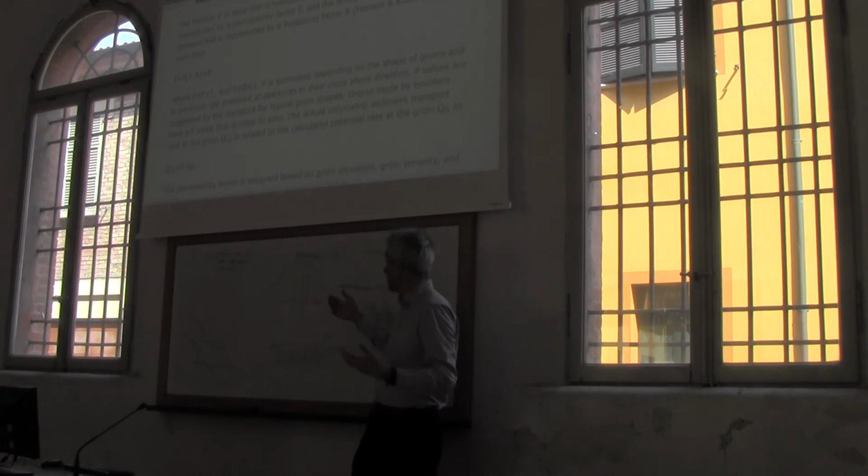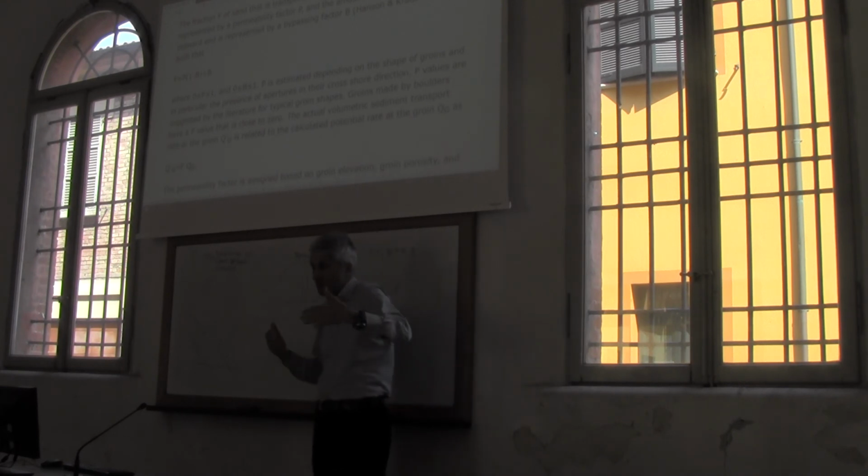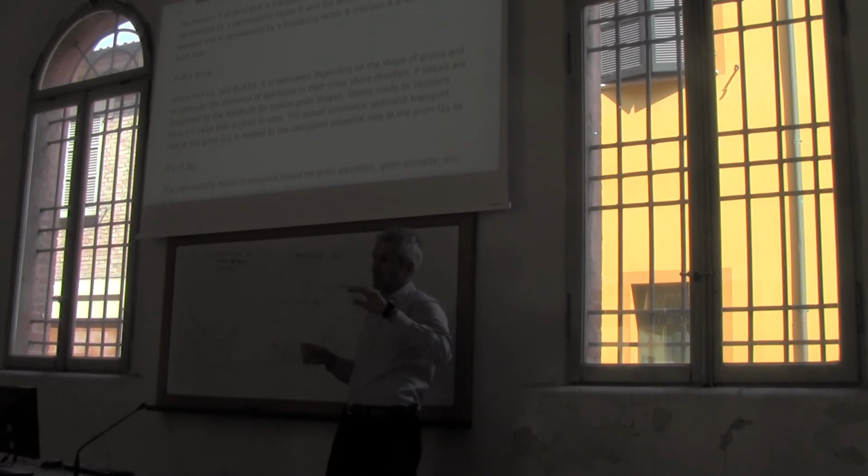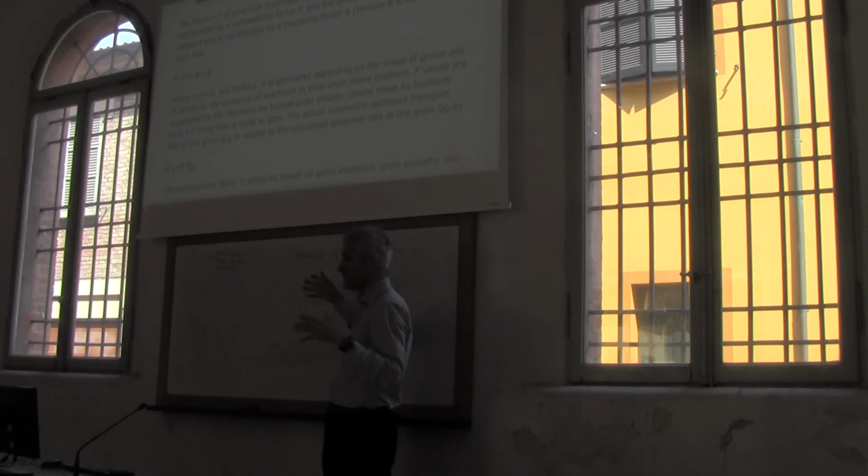In order to get a perception of bypassing, what you could do is to look at what happens nearby, if there are other groins, if there are other batteries of groins. You may try to understand whether there are signs of bypassing. And for instance, if there is bypassing, what happens basically? You have sediments that pass through, and then after the groin, there is less turbulence, because the strength of the wave slows down, and therefore you have the deposition here.